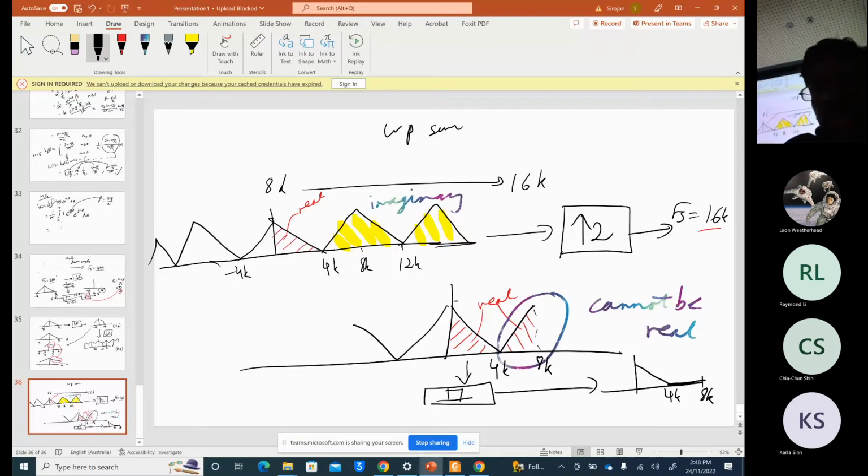So what is the cutoff frequency here? What should the cutoff frequency FC be? The cutoff frequency has to be 4 kilohertz. Why? Anything higher than 4 kilohertz, we have to remove. And what is theta C in the digital frequency?